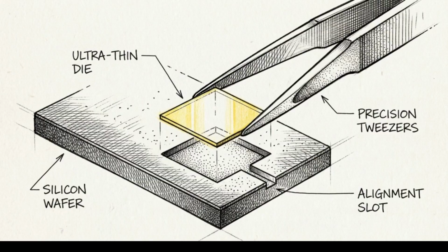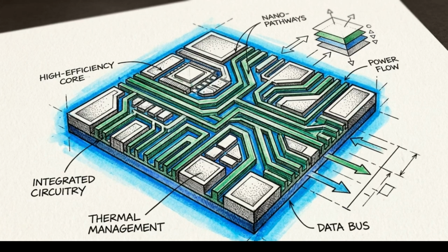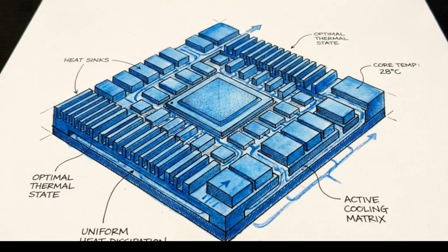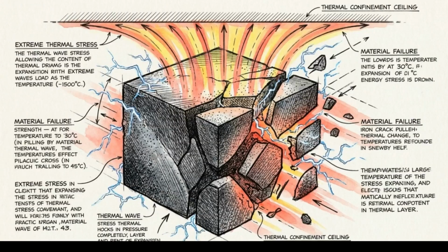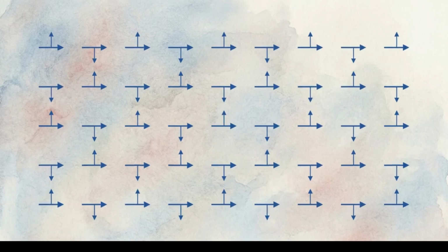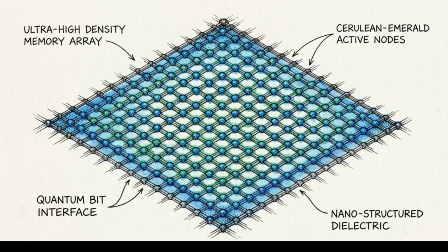Resolving these material science challenges directly translates to significant energy and thermal efficiency gains for large-scale integrated circuits. Remaining tied to high resistivity heavy metals and standard spin-orbit coupling ensures a hard thermal and electrical ceiling on integrated circuit evolution. Transitioning away from traditional spintronics to master momentum space orbital texture provides a technically rigorous path towards sub-nanosecond, high-density non-volatile memory.